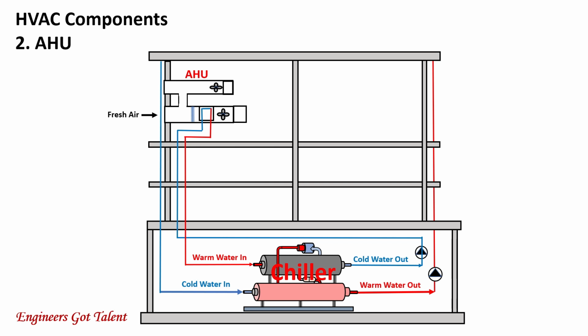summer. It also has heating coils to heat the filtered air to be supplied to the rooms that need heating during winter. The AHU adjusts the temperature and humidity of the filtered air and then supplies a comfortable and refreshing conditioned air into the rooms through the ductwork. The dirty air coming from the rooms is sucked and ventilated outside of the building, thus the name ventilation.